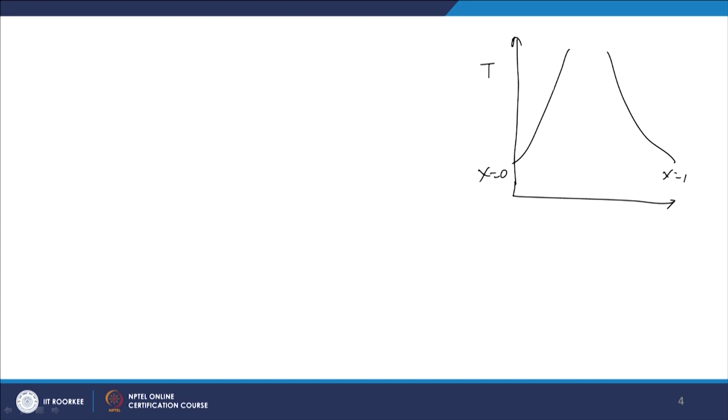First of all, we will draw the ideal Rankine cycle. Here in this Rankine cycle the steam is obviously superheated. If you look at the steam table at this pressure of 140 bar and 550 degrees centigrade, you will find that the steam is superheated. So if you draw the Rankine cycle on a temperature entropy diagram, this is x equal to 1, and the diagram is going to be like this: 1, 2, 3, 4 and this is 5, and the direction of the process is like this.